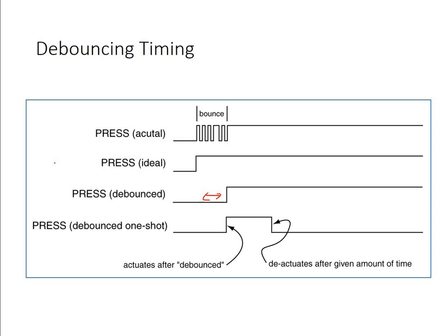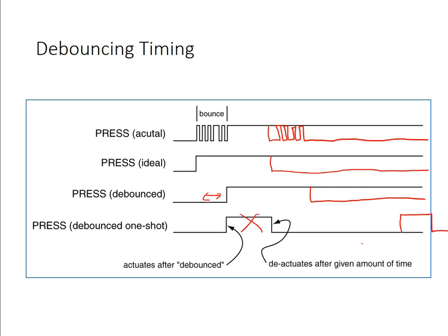And so this is what the debounce one-shot module is doing. It's a finite state machine that at the front end is going to ensure that the signal has actually gone from low to high, the debouncing. And then once the signal has gone low, the debounce one-shot module will, after some delay, give a single cycle with the output high and then back to low. Note that with our debounce one-shot module in the auto wrapper, this could be somewhere around 100 cycles later from the point where you actually push the switch.